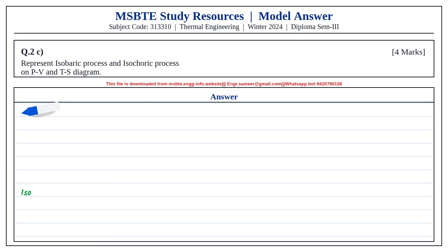Substituting values, Q by A is equal to 250 divided by (0.02 by 58 plus 0.005 by 0.116). This gives 5754 watt per square meter. Therefore, the rate of heat flow is 5.754 kilowatt per square meter area.